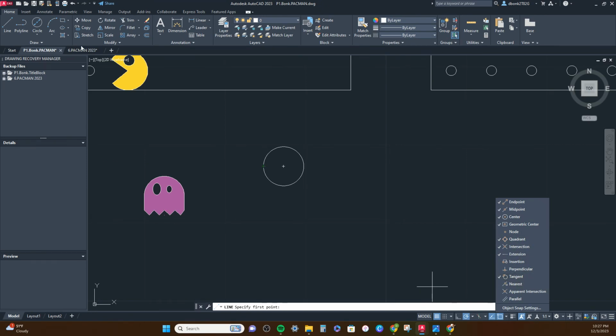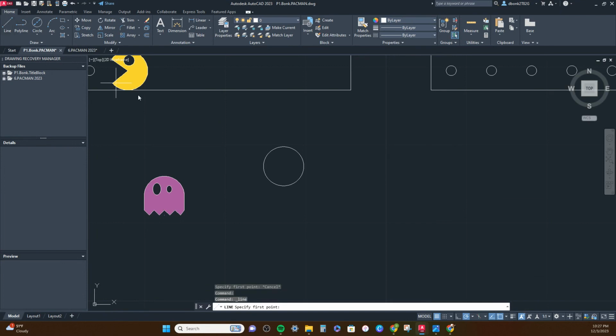Yeah, and what that'll allow you to do is, when you're going to draw lines now, you hover over the outside edge of this. It's going to draw a tangent line. What you want to then do is mouse over the bottom edge of that circle and back to the corner over there. And then do the same thing. You're going to go out here, go up the opposite edge of that circle, and use the tracking to find the corner point. Back up. Hit the escape key. Done drawing the overall.